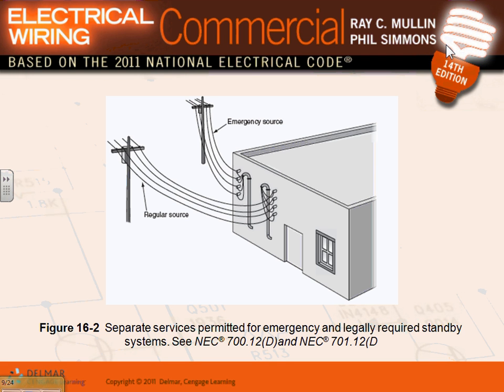Now, this does not meet the emergency code though. You need two sources of power. They allow you, for hospitals commonly, to have regular power and emergency power, so basically two utilities coming to your building. This does not meet the safety code though. But the NEC allows you to have two sources of power, one emergency and one normal, instead of having what? One generator, one source of power.